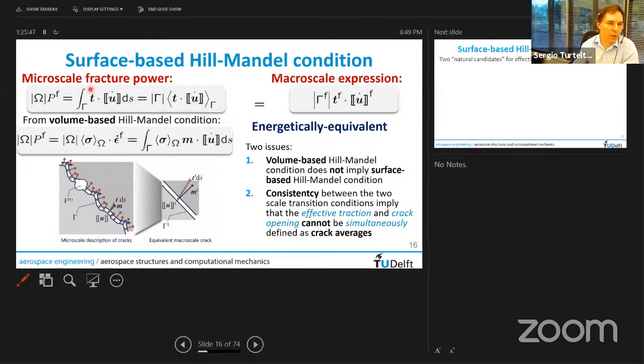And then what we do is that we integrate. So we take the total along this crack by taking this integral. So we first need to identify where the crack is, which we have an algorithm to do. And once we identify that, including all little branches everywhere, we integrate that, and so this is the average of the product. It's the average between the traction on the crack surface and the crack opening rate.